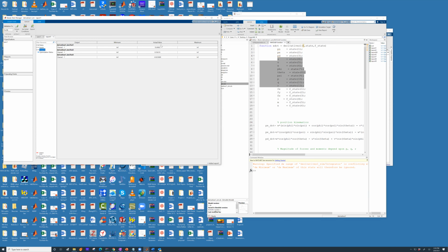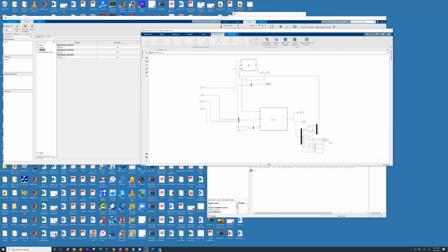My outputs are here, and I want you to look at this output closely. Channel 1 output is nothing but my airspeed. Can you notice that my airspeed is fairly close to the forward velocity that I specified, which was 10? Initially, I set my state u equal to 10, and I got an output of 10.49. Then the derivative one comes from this output state.